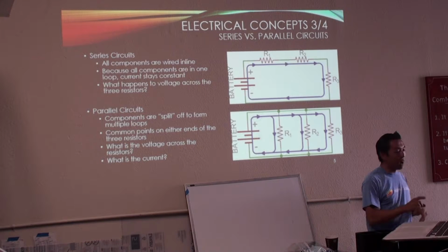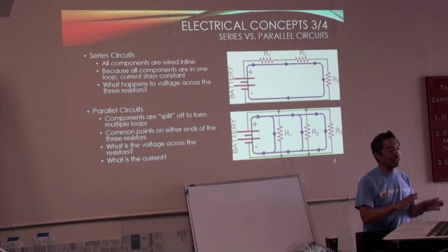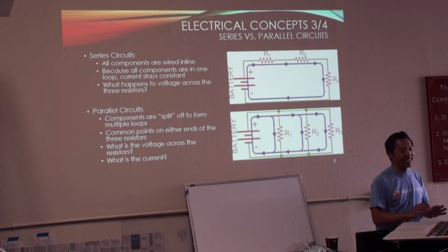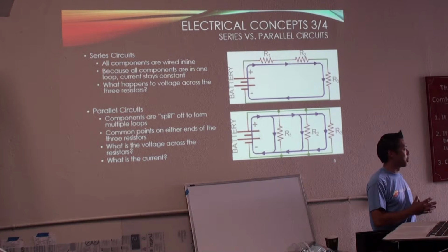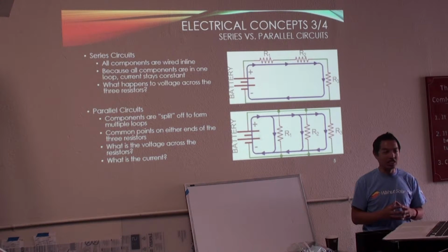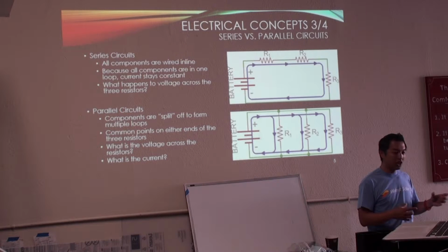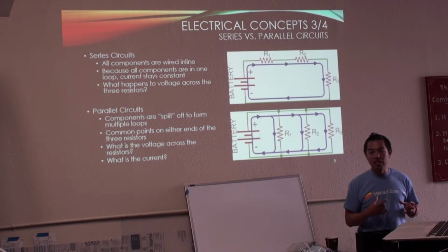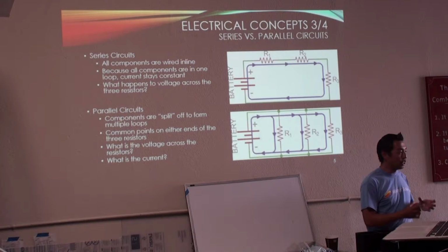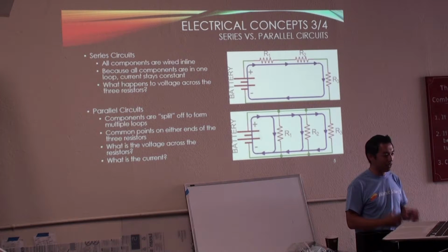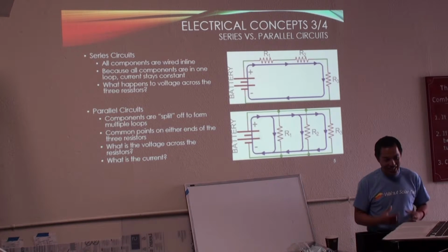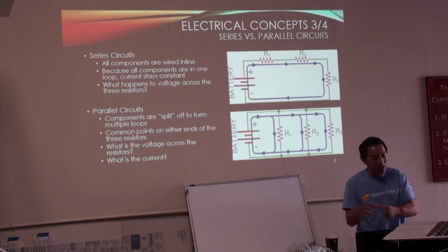Well, batteries are actually wired in series parallel. We'll talk about that in a sec. But the thing that's wired in series is our solar panels. Each solar cell is wired in series, because each solar cell produces half a volt, and half a volt you can't do anything with. So you add a whole bunch of them together.